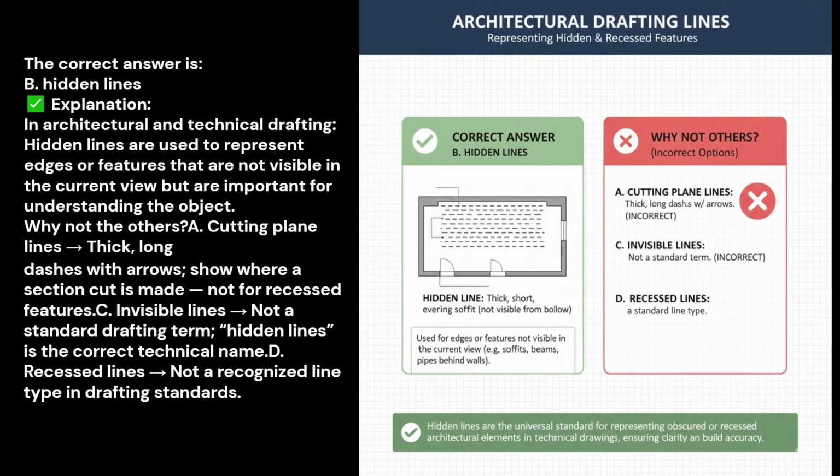While line weight can vary by standard, hidden lines are often medium to thick, not as thin as centerlines, to ensure visibility, especially when indicating recessed or obscured construction elements in plans. In floor plans, a recessed ceiling, bulkhead, or alcove that isn't visible from above but affects the space below is commonly shown with hidden lines. Thus, a recessed object, e.g., a soffit or niche, is indicated using hidden lines matching the description, short and thick dashes.